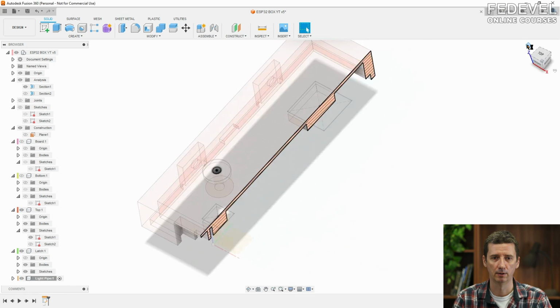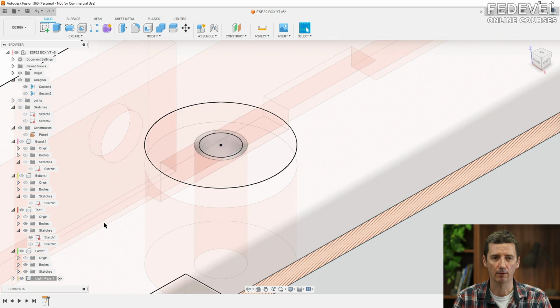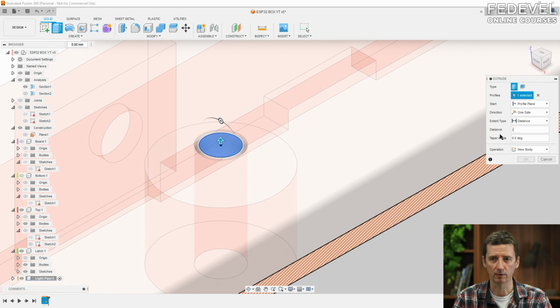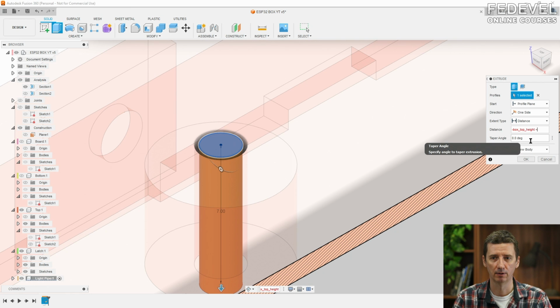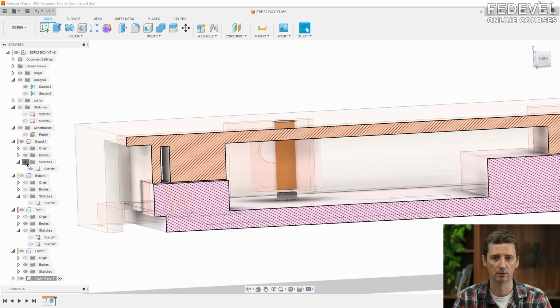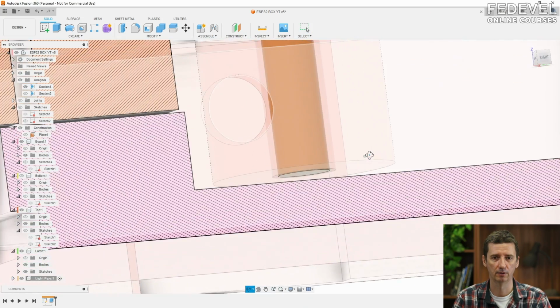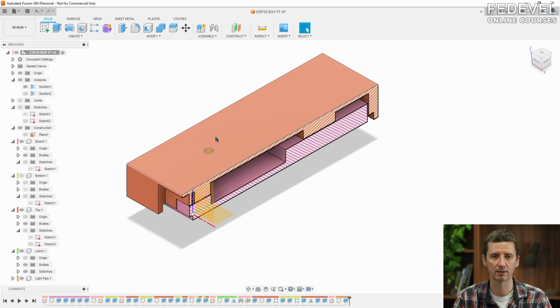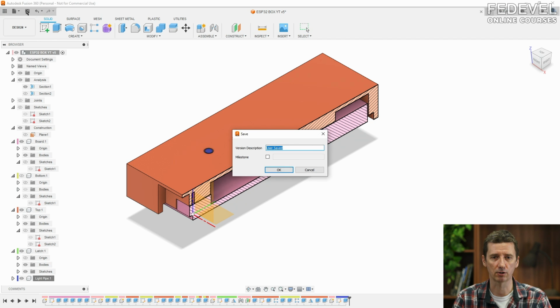and now use the extrude feature, and we would like to have this pipe, this light guide, we would like to start it just above the LED. Like this. Okay, double check again everything. Perfect. If you don't have clear filament, it's fine. You don't have to put it there, but it looks very nice with the clear filament. If you don't like the colors, you can always change them.